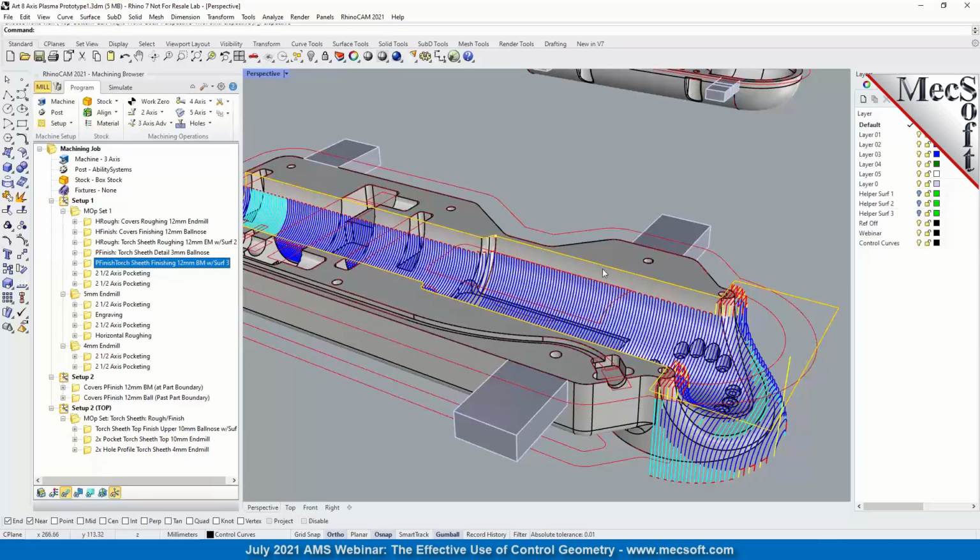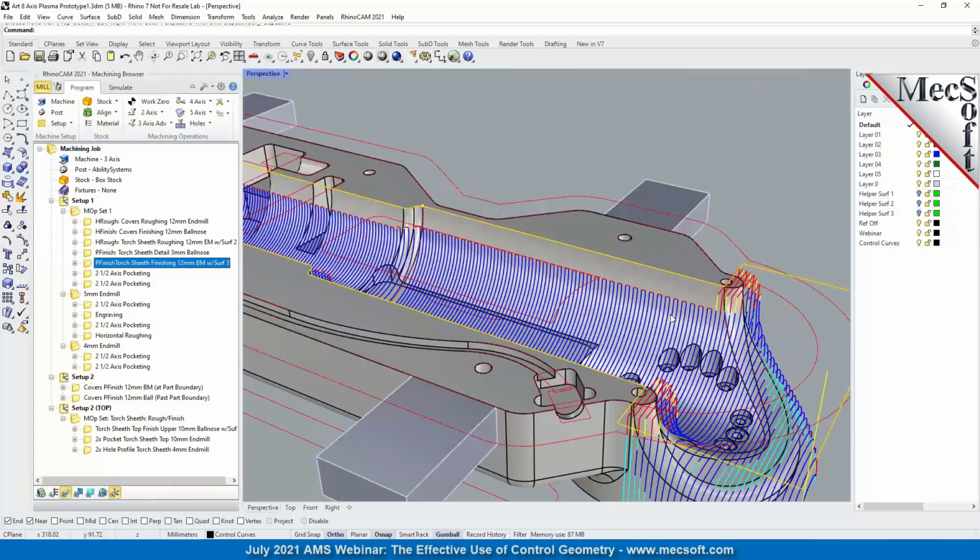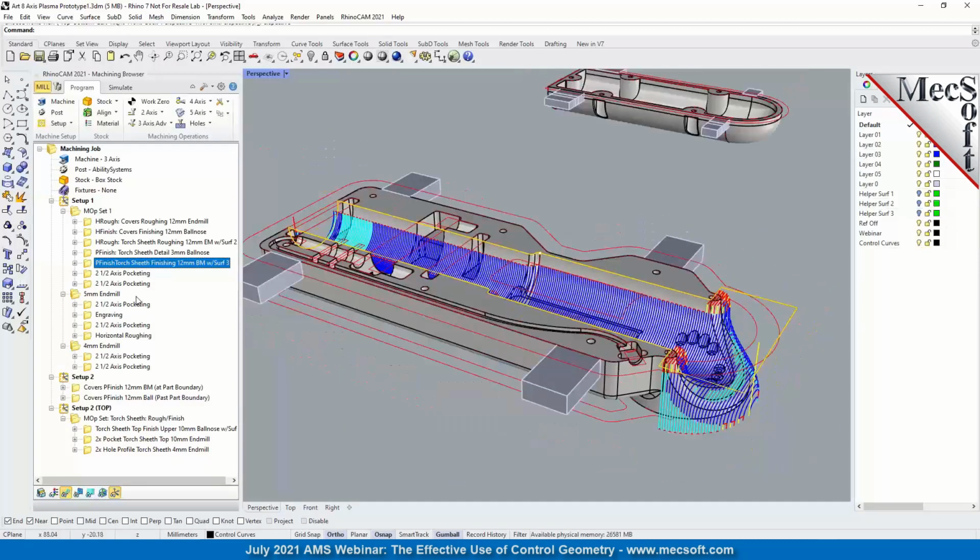So every time you go up to this edge, the ball will roll on it till the tip of the tool actually touches this edge, which means that you're degrading this edge every time that ball moves from one point to another on the same edge. So we contained it in the Z-axis and also contained it around the front here. In these examples, we've loosened up the step overs so you can see the tool path. Obviously, in their production parts, the step overs are much closer and more dense to get a better surface finish.